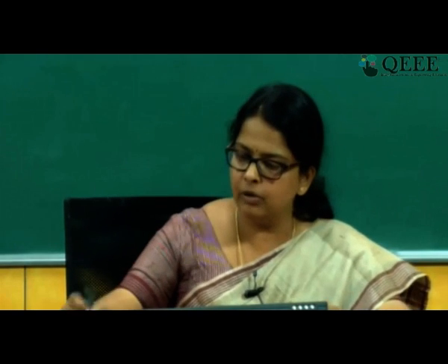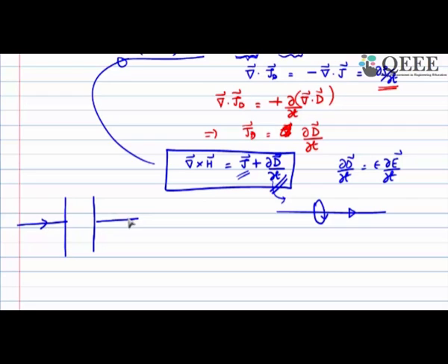I see, how do you justify current flow through a capacitor? So you have already answered the question. The current flow through the capacitor is justified through this del D by del T. So in a capacitor, by asking that question, you have already answered the question. There is an electric field, let's say this is the plus plate and minus plate. So if I have a time varying field, there is del D by del T happening here because the electric field changes as a function of time, and the displacement current, this is what we call a displacement current, flows through the capacitor, which is providing a continuity.